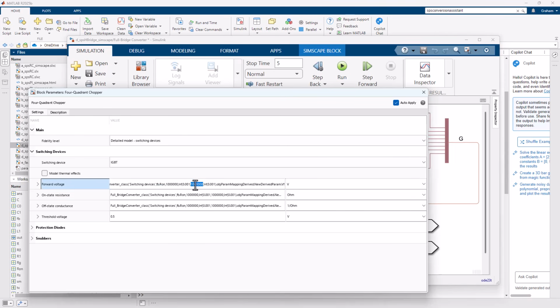You could go in there and type FB.ROFF, but that is a change that you may or may not want to make. With the off resistance, not so important for subsequent use. RON may be what you're wanting to change, but you can make those modifications. And this is why the manual inspection is important, so you can assess the parameterization and make changes as you see fit.